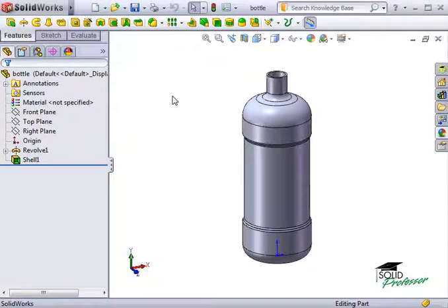First, you have to create a helix that defines the thread pitch. Second, you must define the thread profile. Third, you must terminate the thread to eliminate the abrupt ends. Let's begin by creating the helix for a sample thread.